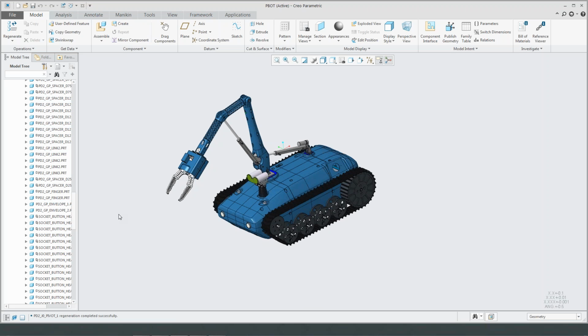Why we have that in Creo Parametric is because there are some areas where a parametric modeling tool falls a little flat or slows down or becomes a little more complicated, such as when you're working with non-native CAD files. If I were to bring a file in from SolidWorks, per se, a lot of that information doesn't come over. You just get an import feature. You don't get the whole model tree. So how do I make modifications to that? Well, a direct modeling tool where it's just looking at geometry is the answer. Another area is if I want to simplify a model down for analysis, I don't really want to worry about all the parent-child relationships I've created. I just want to remove rounds and simplify a part down. So again, direct modeling is the key.